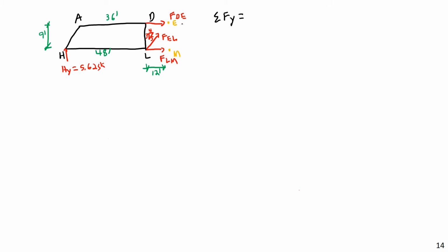Also, important to note, you will note that I drew all of these assuming tension. I drew them the exact same way I did in the method of joints when we were looking at that in lecture 9. And so I initially just assumed everything is in tension. I assumed all the forces would be positive. And then if I get a negative number for one of the forces, I know that force will be in compression rather than in tension. And of course, this is just for trusses. Later when we get to frames, things will be a little bit more complex.